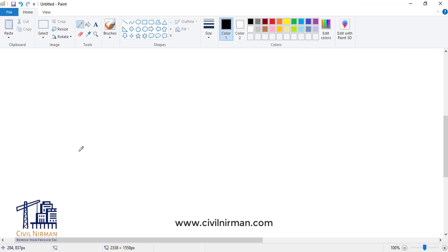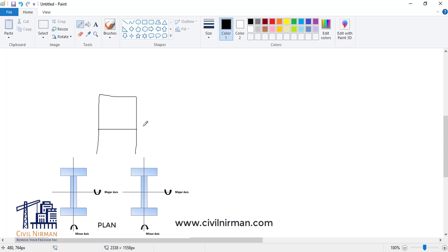So going back in Paint, when we have a portal frame and there is a member over here. Now, if we are talking about Ly first, and if this is a minor axis in this direction, then with a moment connection, which is rare in a minor direction, but in case it's there, we can define this particular length as an Ly length. And same way on top, if another moment connection is coming, then this will be another Ly.